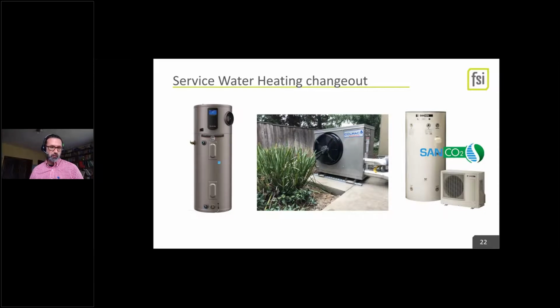The one in the middle is an outdoor heat pump. Just like the hydronic version of air to water heat pumps, it has capacity limits at low ambient temperature and often requires a backup. And what we found in past projects is that they are extremely finicky on exactly how they are piped to things like storage tanks. So something to really get into with your rep, like if it's your first rodeo, make sure that you have gotten deep into it with your rep and maybe even called the company whose equipment you're using for the project.